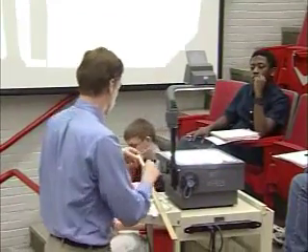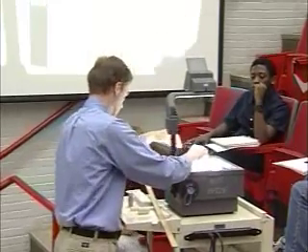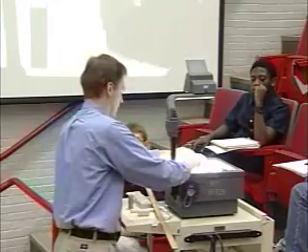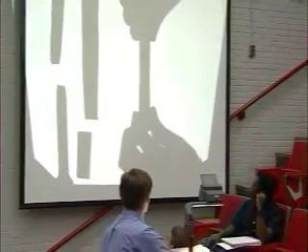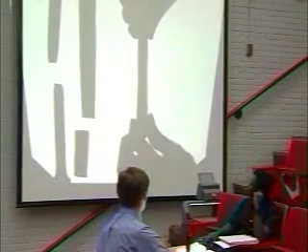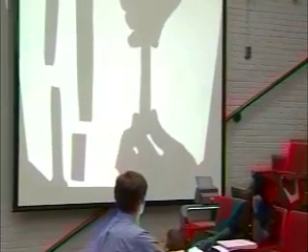A couple more, just if you didn't see what I did then. This is modeling clay, and I'll try and load it just so you get the idea of what's going on. You see it's thinning down, it's plastically deforming. And it necks down nearly to a point as we're drawing out material. This is actually a plastic instability, and we'll talk more about that by the end of the lecture. So there are different material behaviors here. There's this sort of plastic response, and then there's a brittle response.